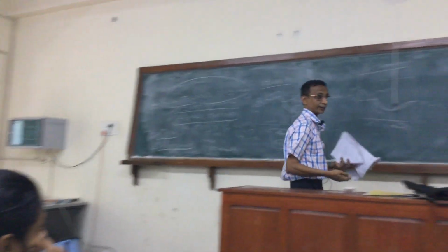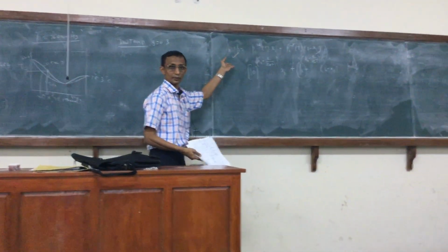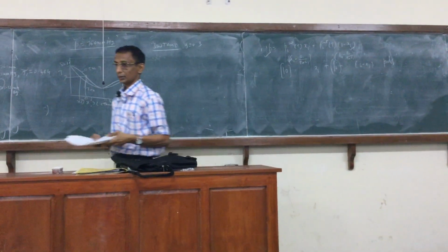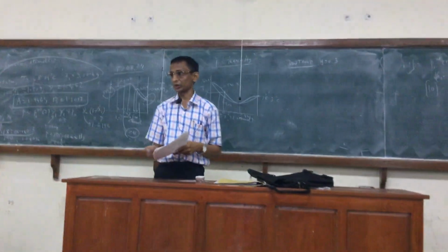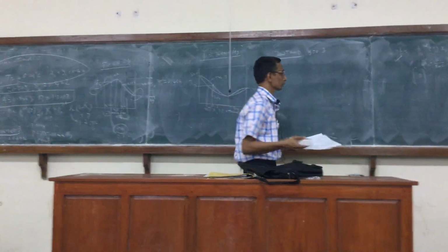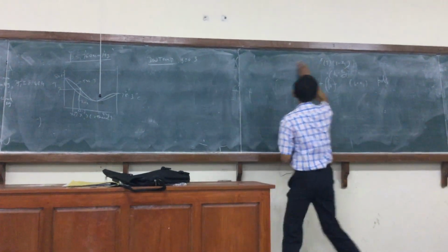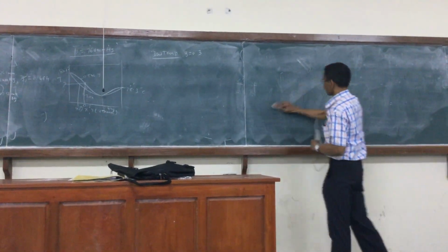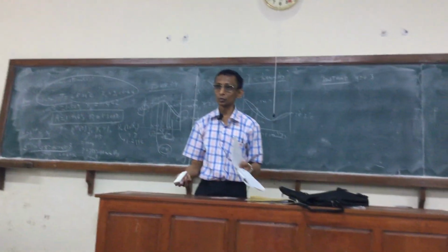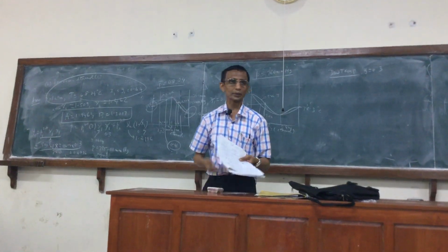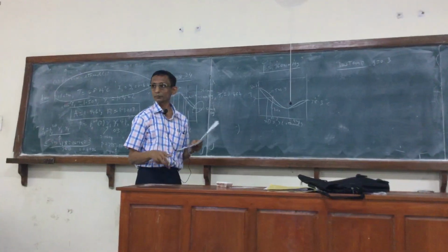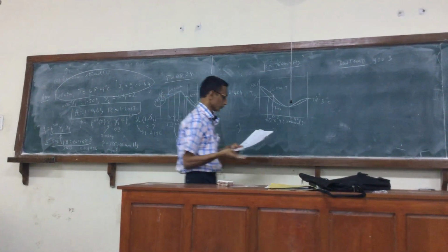Fine, what you're saying is correct. You get one equation, but you still have to solve the non-linear equation. This still requires an iterative procedure. Right? And you have to solve it using one of the standard non-linear equation solvers. That's also perfectly fine. There are also some books that have actually given that, and they might have to go again and do an iterative procedure to solve it. But the one I have given is probably more widely discussed algorithm. So we'll just work it out for the dew temperature.